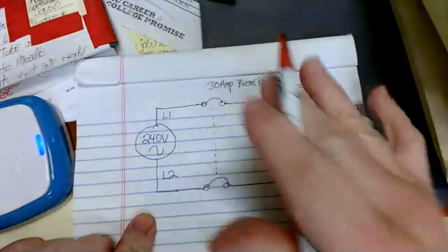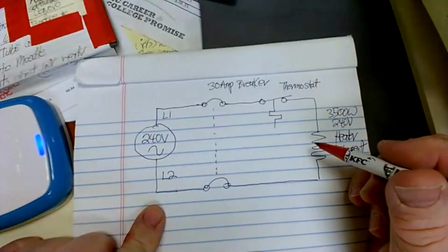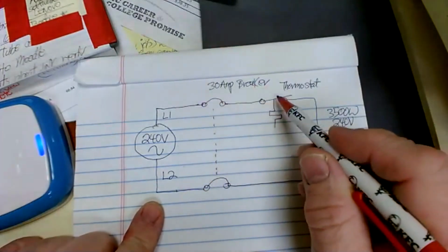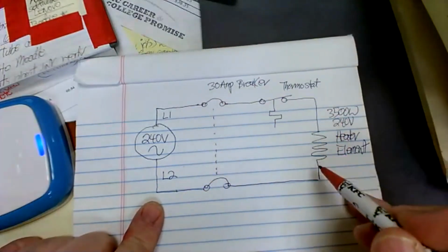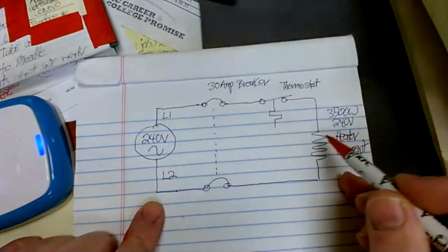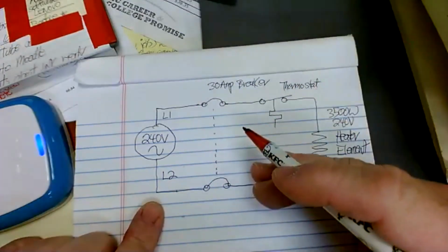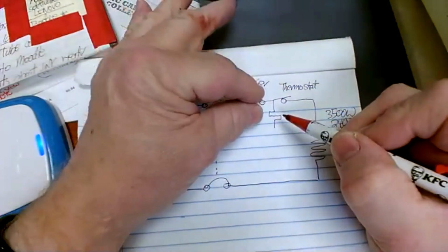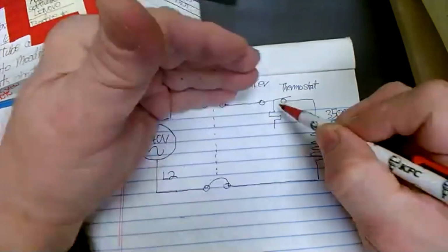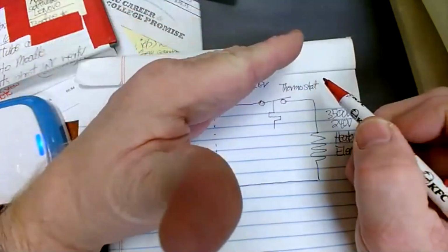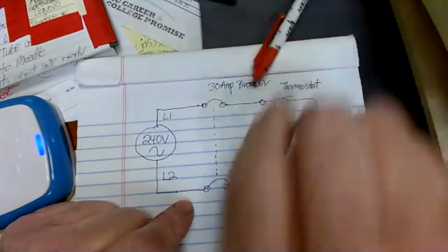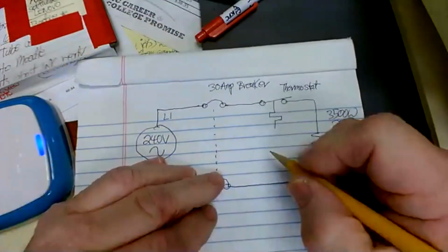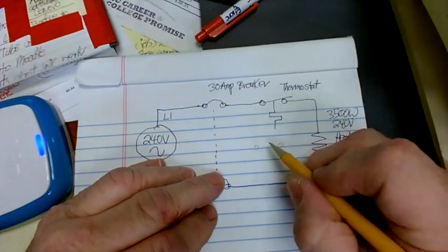when you start out, the water is going to be cold in the water heater, right? And power is going to run through here through a normally closed thermostat, and it's going to circulate around. And then this is going to get hot, and eventually the temperature of the water is going to build up. And when it does, that thermal sensor is actually going to spread, and it's going to cause that contact to raise and open. So at that point, here's what you would have. When it opens, it looks like this.